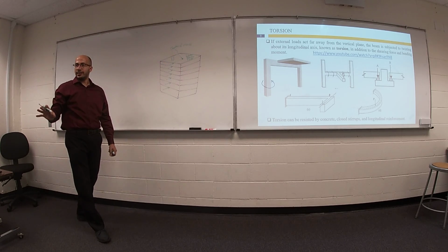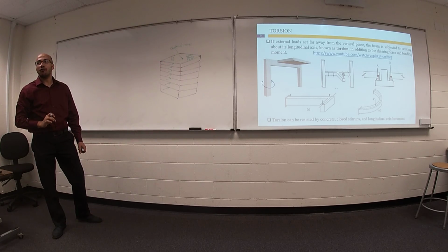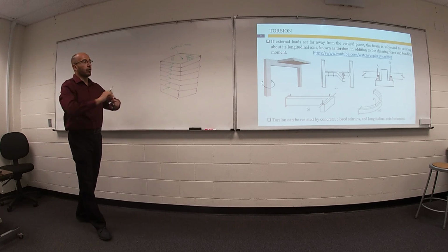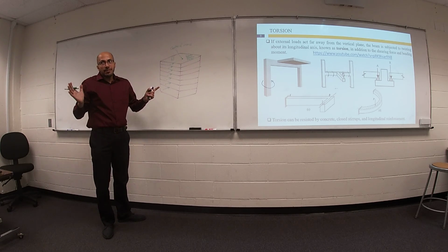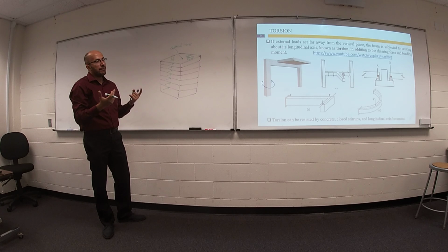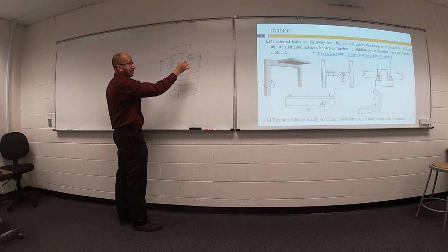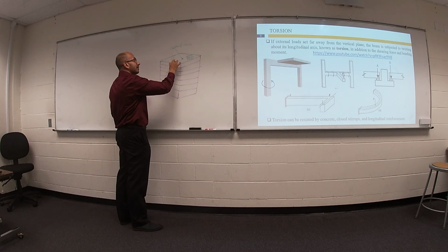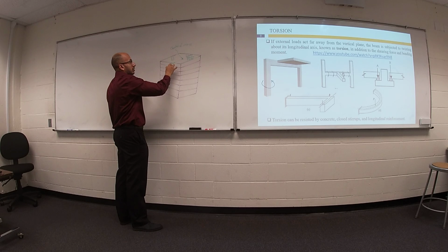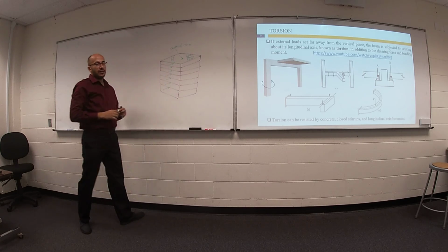Where is the center of mass? Where is the centroid for all of these loads? Maybe at the center of this area, maybe not. Anyway, at the center of all of these weights is the point of application of your earthquake force at each floor.